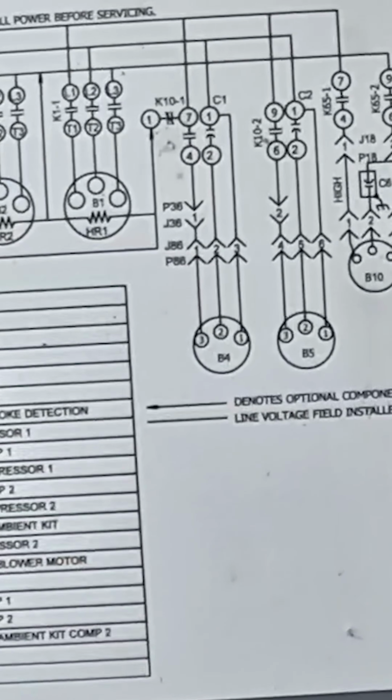Alright, so hopefully that helps you guys a little bit too on the relays there. You can understand the power's coming in on the common side of the relay, and it'll either go there or there, depending if the coil is activated or not activated. And also I want to point out, we have K10 right here. This is showing the high voltage side of K10. But if we come up here, we can see the low voltage side of K10.